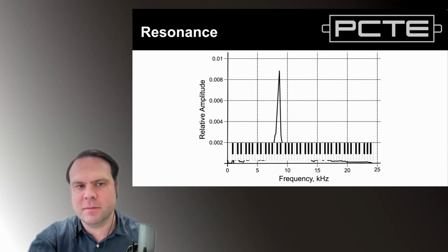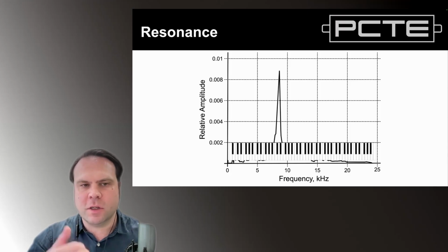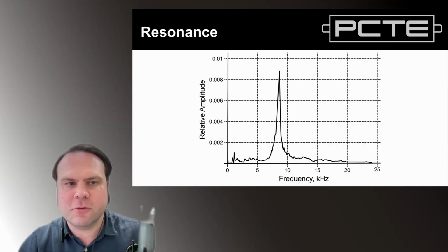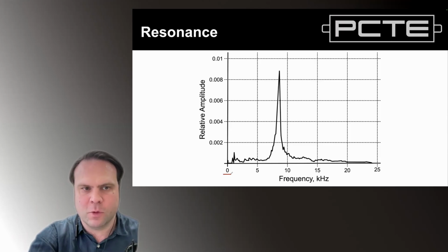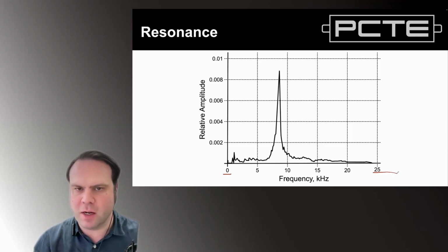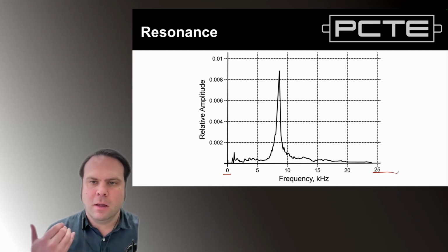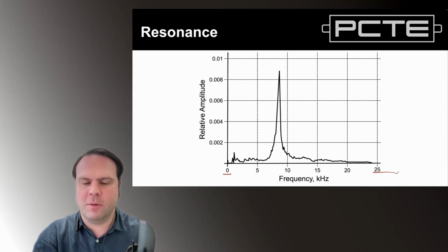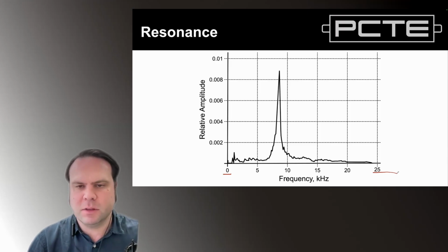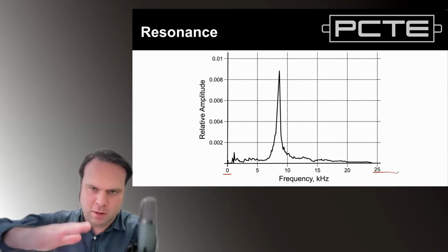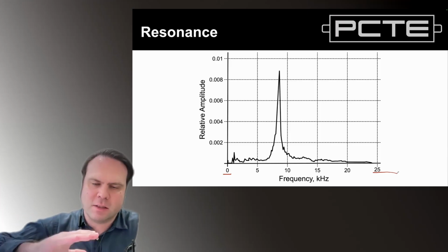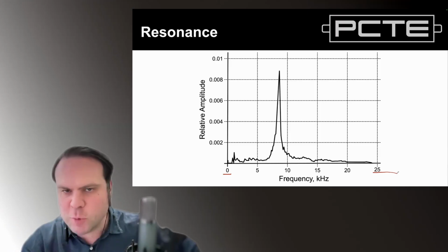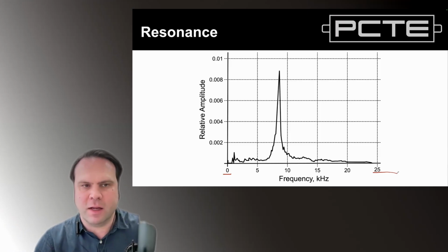Further to that, we also need to capture only the frequencies we care about. So if you look at this chart, we can see we go all the way from 1 hertz on the left to 25,000 hertz on the right. But not all of the energy from our impact is sound. Some of it is effectively motion, wholesale vibration of the sensor or the concrete itself up and down, which will be detected by the broadband sensitivity of our particular systems.